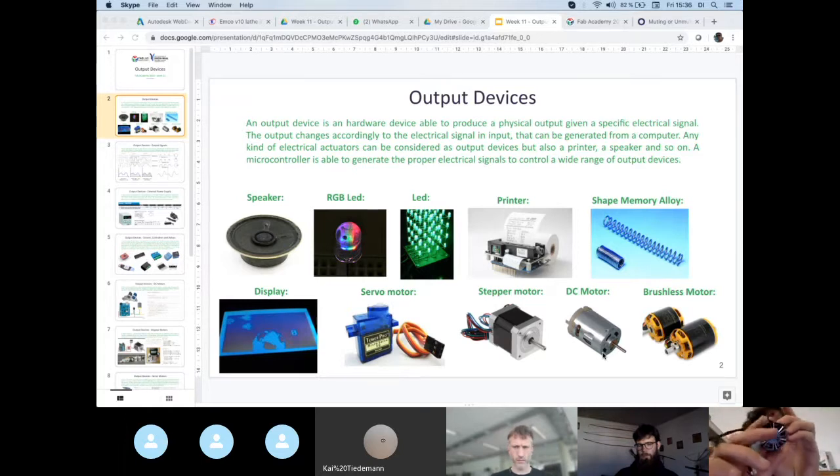The complexity that this creates inside the construction of the motor generates the need to have different signals for each coil of the motor, because you don't have the brush inside that changes the direction of the flow of the current in order to keep the motor rotating.